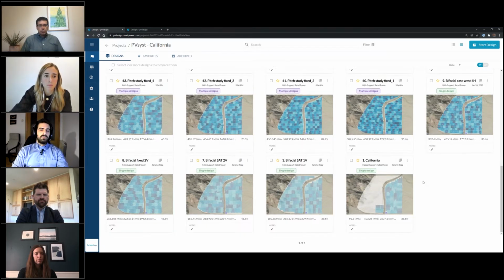Well, mostly it depends on the inputs, as usual. If you set up accurate inputs in both, the same meteorological data and, in that sense, good quality meteorological data, you will get very close results. Obviously, the simulations need to be equivalent. It doesn't make sense to compare a PVsyst simulation using 3D shading with PVDesign, because PVDesign, as of today, does the shading seen in a flat terrain. So you can really compare the two if you're doing flat shading in PVsyst, right? But other than that, I'd say it's really accurate as long as you have good meteorological data in the simulation.